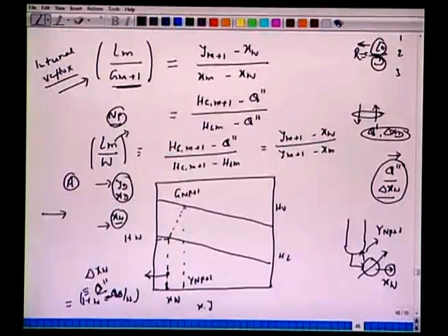The first line which you have drawn, again we can put B. If you recall, B is equivalent to your C there. This reboiler acts as a theoretical plate. So, this is a theoretical plate, and the first plate of the bottom column, or Np, starts from then onward. So, the first tie line is always the B tie line, and once we have drawn from here to the difference point, we draw like this.